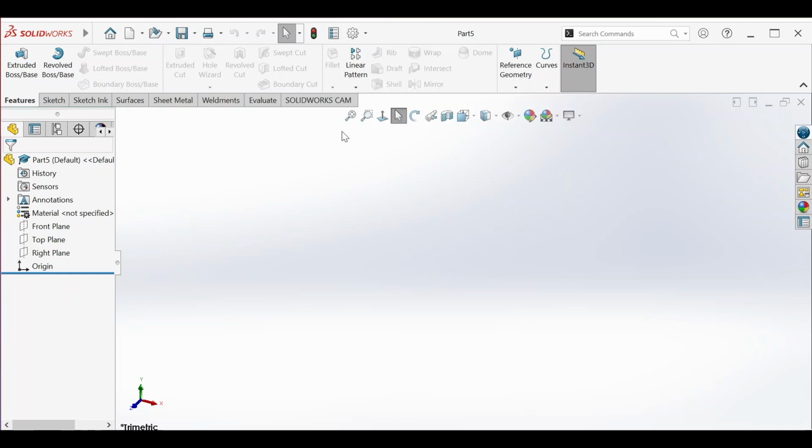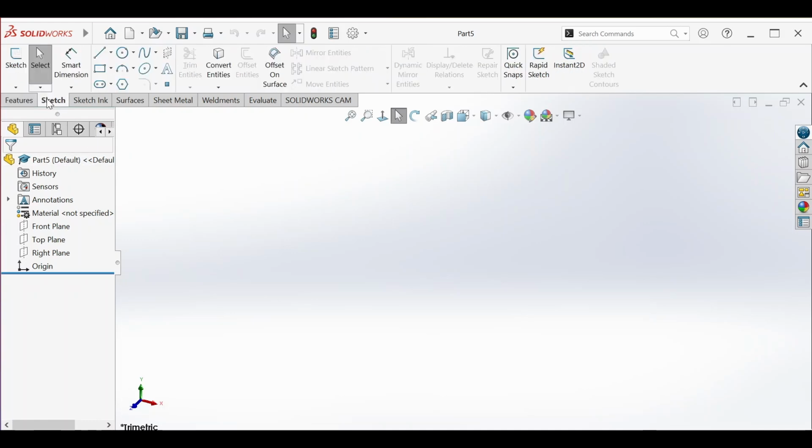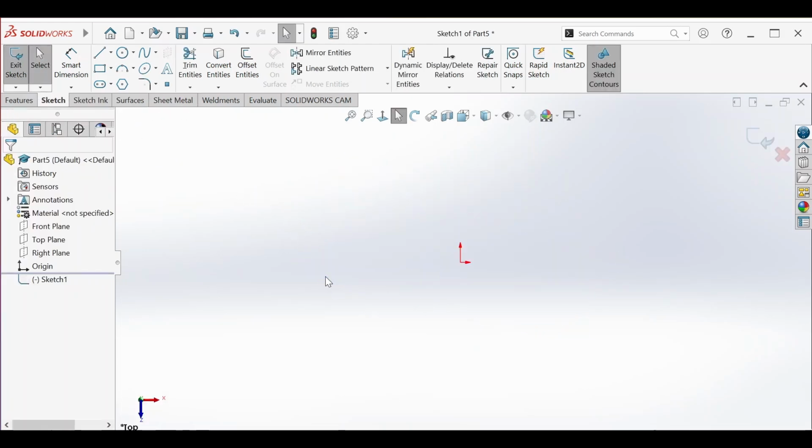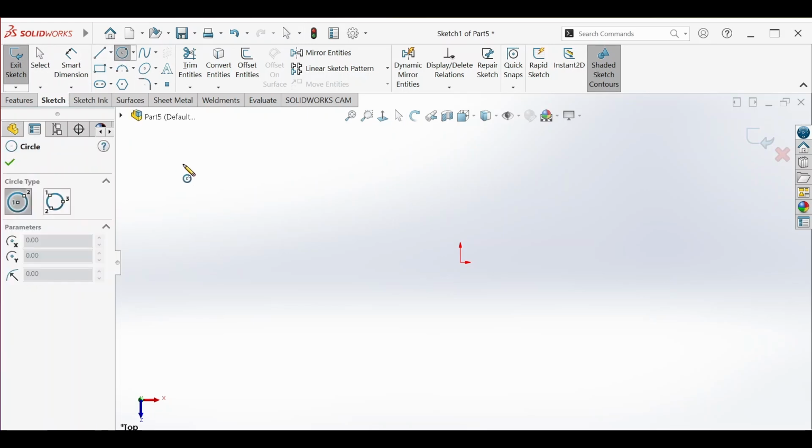They work similarly to the sketch pattern commands, but instead of repeating 2D sketch elements, they allow us to pattern 3D solid features or bodies. To understand how they work, we'll create a gear where the pattern will be used to replicate the tooth. We start by creating the base cylinder. We select the top plane as the sketch plane and we draw two concentric circles.